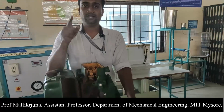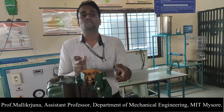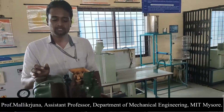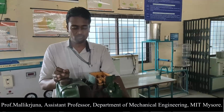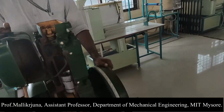So the second reading I am available with now is: exhaust valve opens before the piston reaches BDC. That means before the end of the power stroke, the exhaust valve is going to open. That is the second reading that I have to look onto. I will continue the momentum that I am giving to the flywheel. Exhaust valve is getting opened.